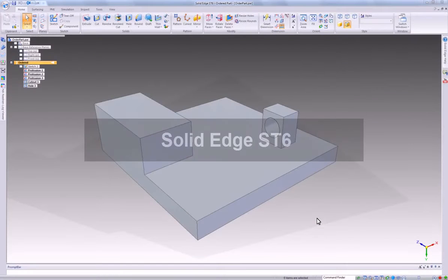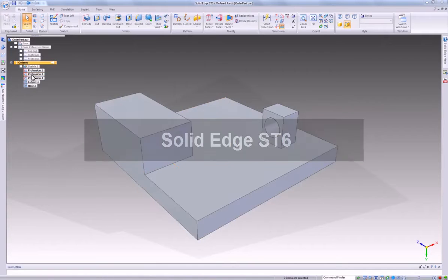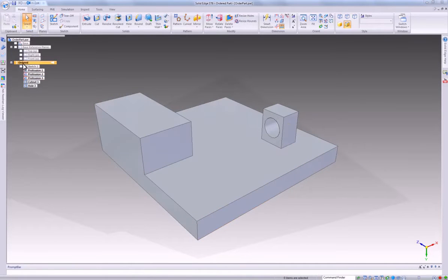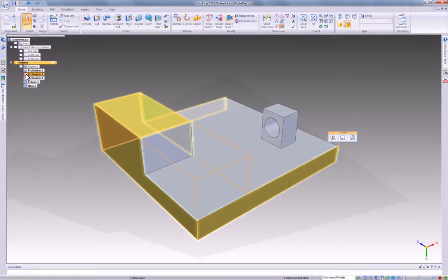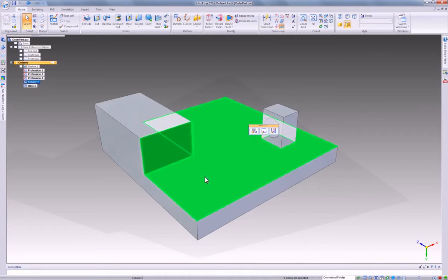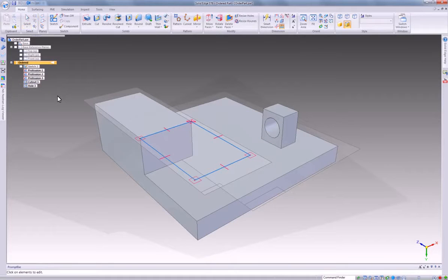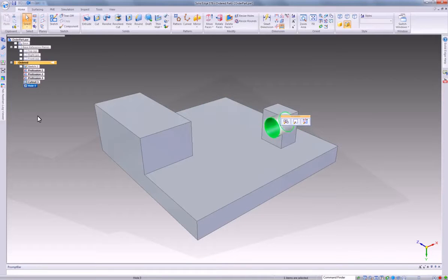This is an example of synchronous technology or other similar technologies. And this is our example case where we have built up an ordered structure that shows a protrusion of a base feature with a block that's extended all the way through to the edge, another solid block that's added onto the right, and then we added our two negative or cut features, one which is cutting this area off here that's straight down. If we look at the profile, it's cutting straight down on this geometry. And we added lastly a hole object here at the end.